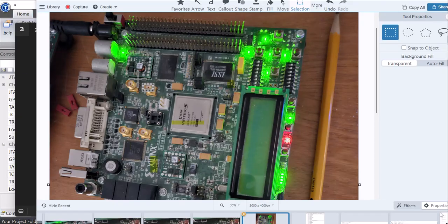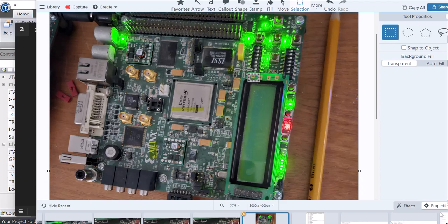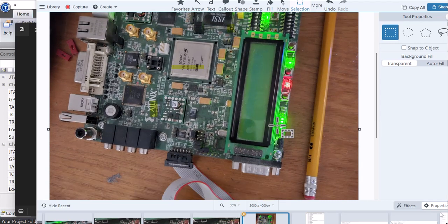We're going to use a Xilinx evaluation board as the target printed circuit board for this demo. The board has 4 boundary scan or JTAG devices on it in a single chain. It has DDR memory, SRAM, and a number of LEDs, some of which we're going to use to demonstrate script programming.